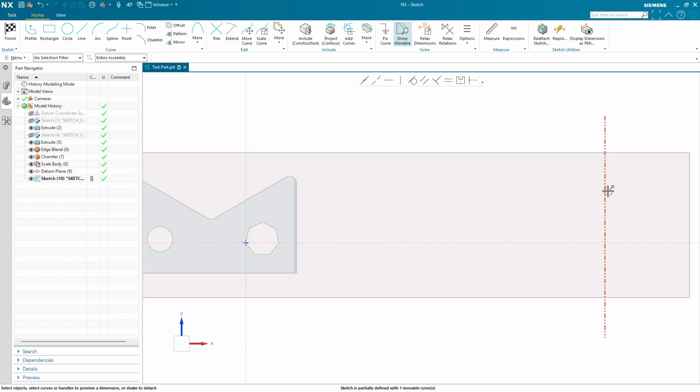So this isn't fully defined yet. It's not fully defined in terms of length, which is 9.8. But since this isn't going to define a part, we just need to have this be vertical and a certain distance away from here. So this is a sort of rare case where the length of this doesn't matter. This can just hang out. There's no reason for this to be any specific length at this point. So we don't need a length dimension. We can save ourselves that.